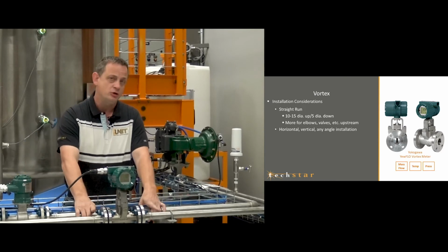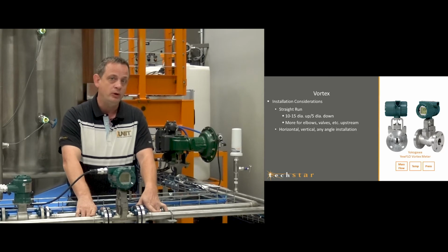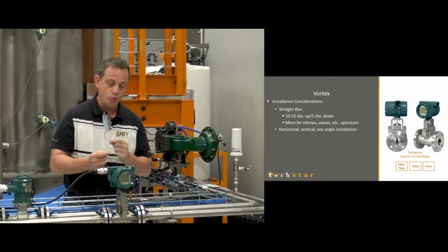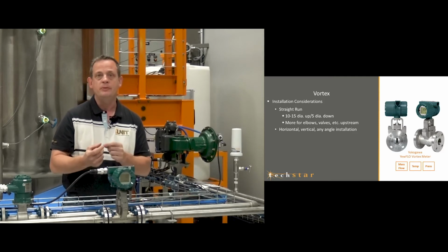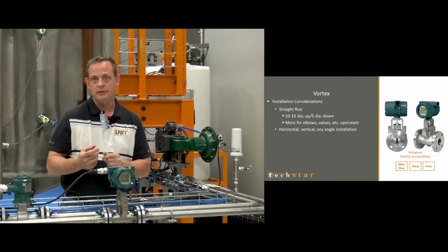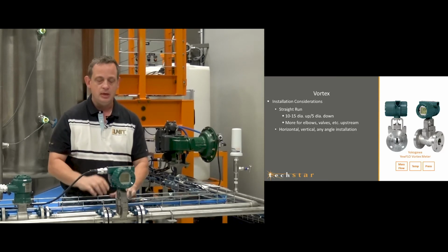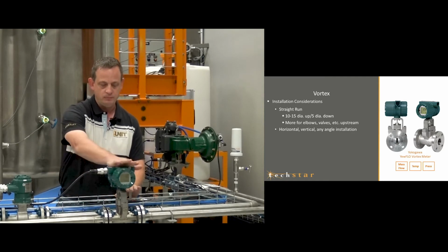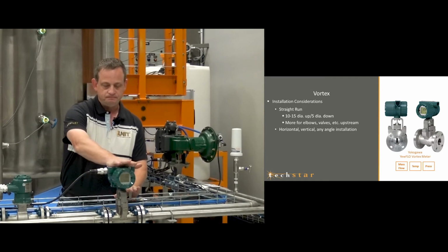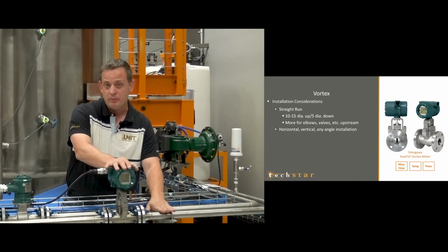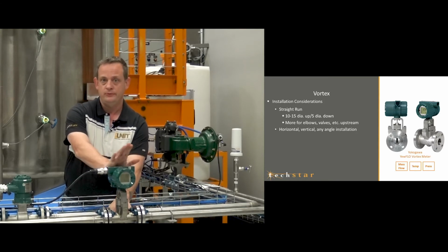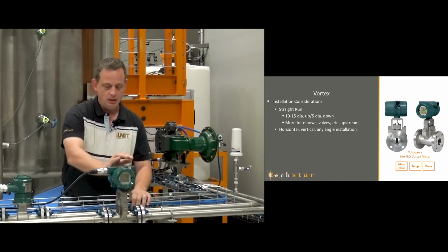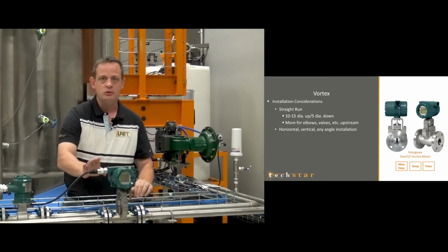And then vibration could also be something that we really want to watch out for on these meters, because these work by basically measuring some of the movement and vibration inside the pipe as swirls coming through. And so we want to maybe mitigate some vibration if there is excessive vibration on the line, either by maybe an extra mount of some sort. Other than that, man, Vortex meter.